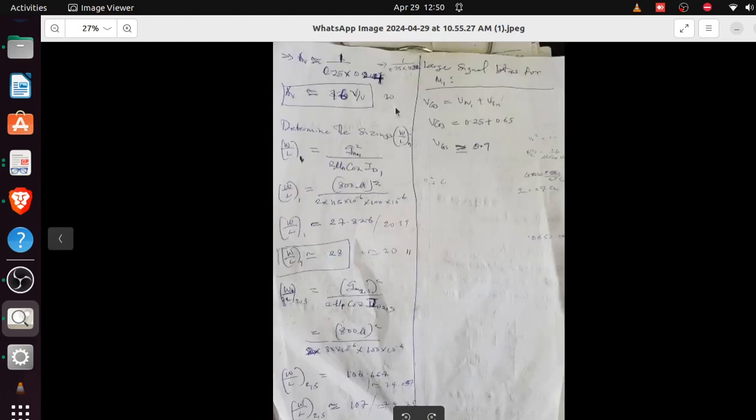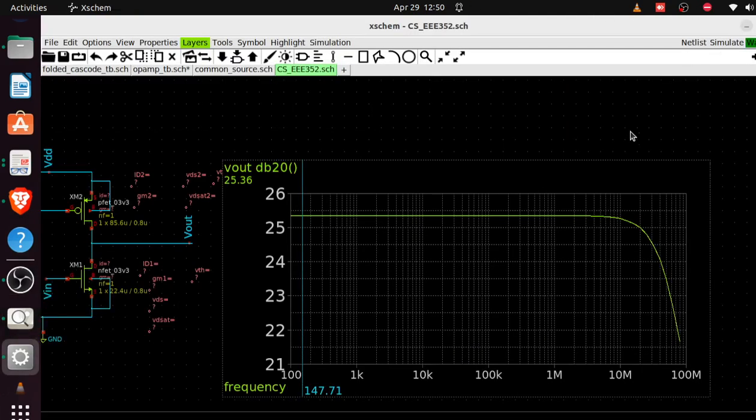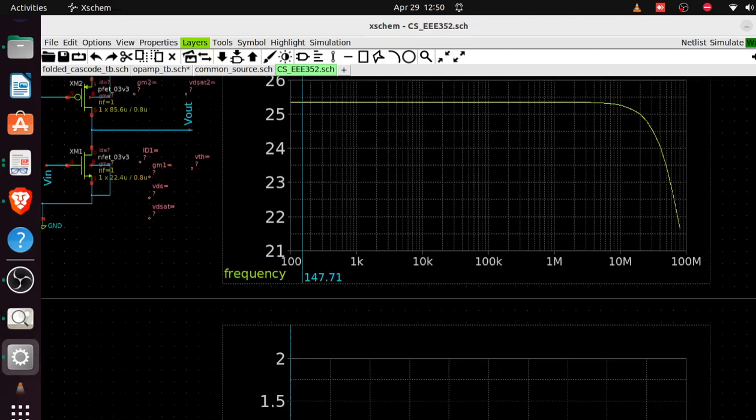Our calculation predicted 16, I got 18. Depending on this value, I think maybe why it got up to 18, maybe the spice wasn't using 0.24, it used something less than that. I think it may be 0.22. If you try 1 over 0.25 times 0.22, yeah, I think that's why. So you see it's still in that range, 0.22 to 0.38. So again, we're all good. Operating points smiled at us. Also now AC is smiling at us.